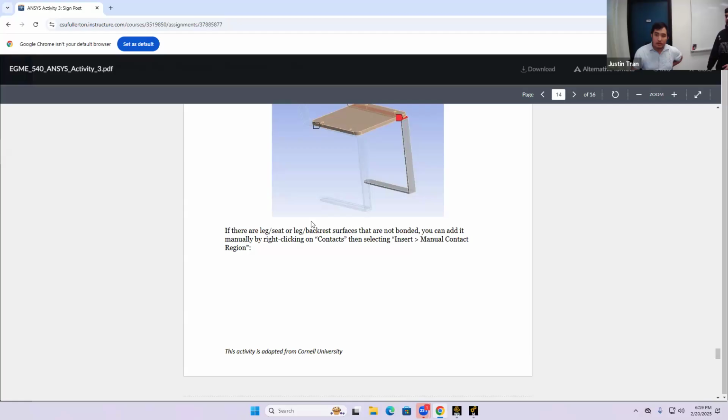Okay. I think it's because right now with your application surface, in that case a 10-inch thing is basically almost like you're adding a steel bar 10 inches thick all the way down. Your application surface is so thick, it's actually adding structural strength to your sign.